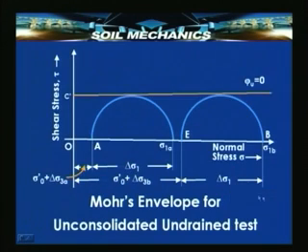If we were to plot a Mohr's diagram based on this, then the Mohr diagrams will be shifted from each other depending upon the sigma 0 dash value and delta sigma 3 that we use, but the diameter of this Mohr circle will remain all the time the same, that is equal to the axial load delta sigma 1 that is applied.